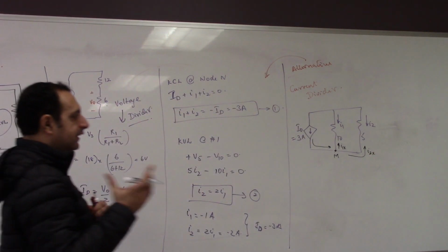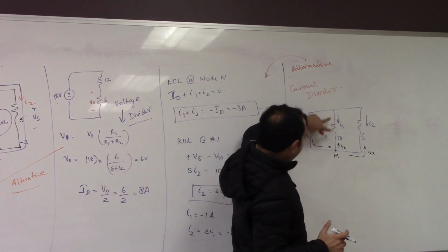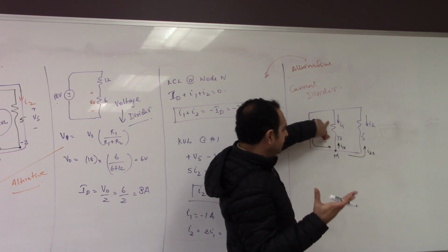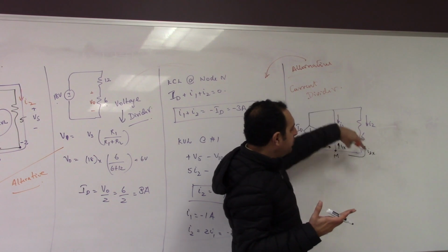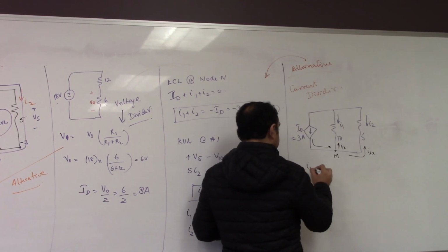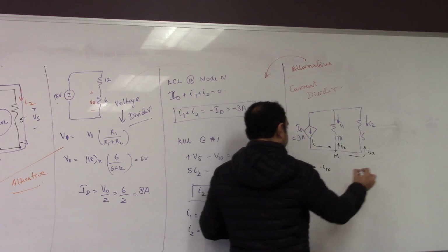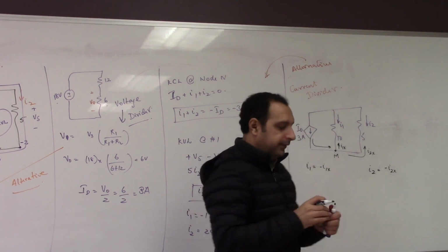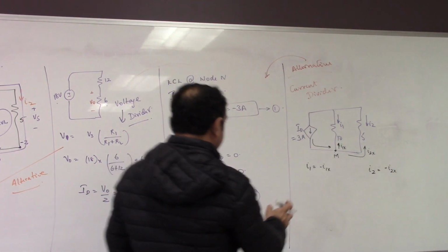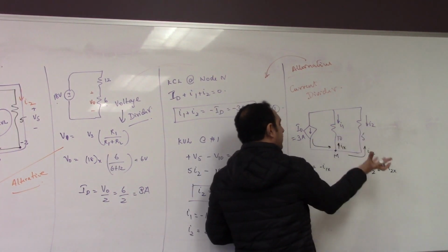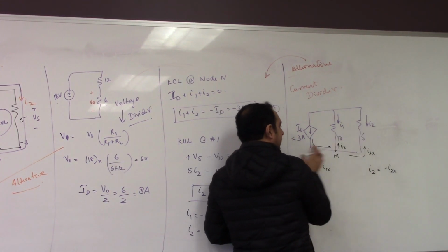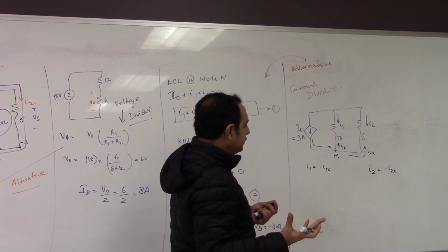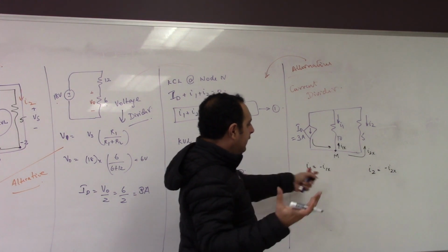All right, I1X and I2X. In a branch, you cannot have two currents flowing in opposite directions. Essentially, they are the same, but since they are opposite in direction, we'll write I1 equal to minus I1X, and I2 equal to negative I2X, because the direction is opposite. This current comes here and it splits. The book has given us directions like this, but in fact the current is flowing in the opposite direction, so we'll write it that way. So by current division, what is the current IX?